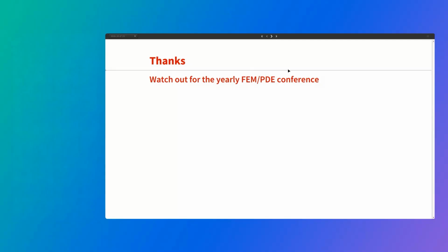Let me go back here. There's a tutorial on element mesh generation that has a lot of material on finite element mesh generation. That's not the entire story, though; that's just for the finite element mesh. You can also use MeshRegion and the top-level or system built-in functions for this. Those are options, and you'd have to play around a bit and see which one suits you best. Start with the MeshRegion functionality first, and when you hit problems, then go to the element mesh generation, because those are really suited for finite element generation.